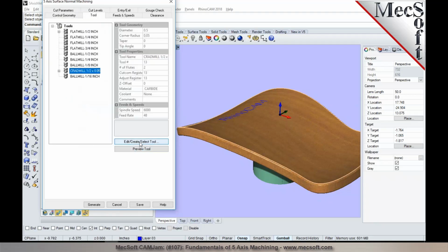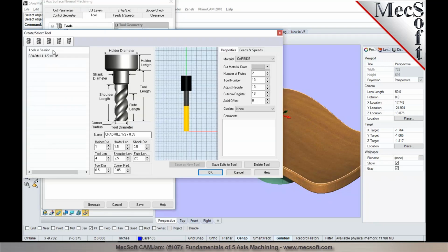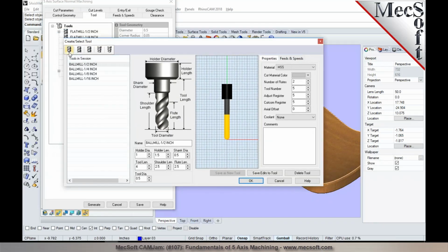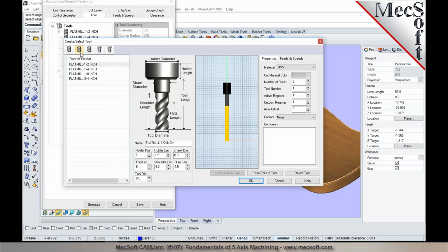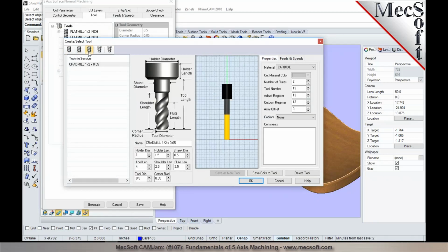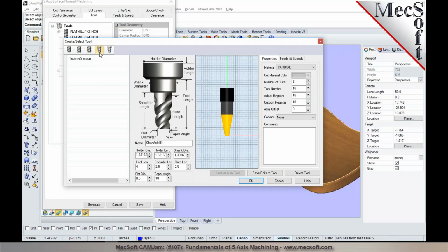Oh, you mean the cutting tool types? Right. Okay. We support ball end mills, flat end mills, also known as square end mills, and corner radius tools. You could have chamfer tools as well as taper tools like tapered ball end mills. These are the different tool types that are supported in the simultaneous 5-axis module.